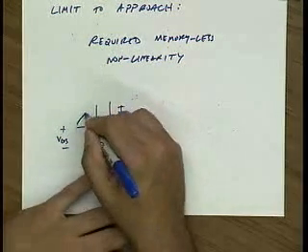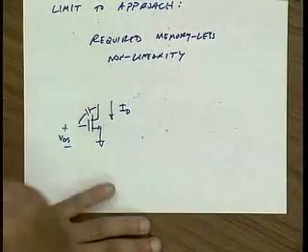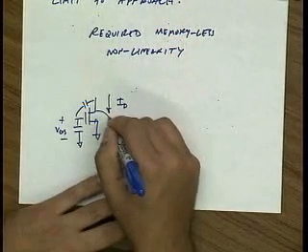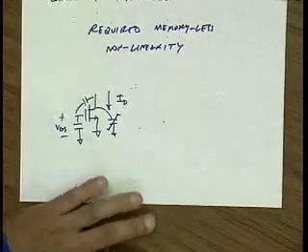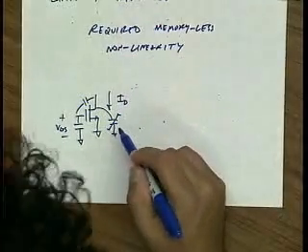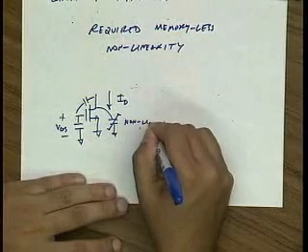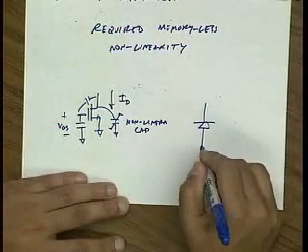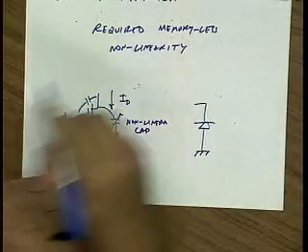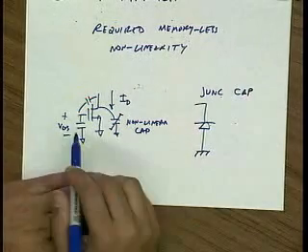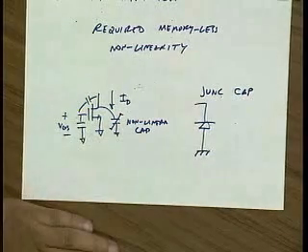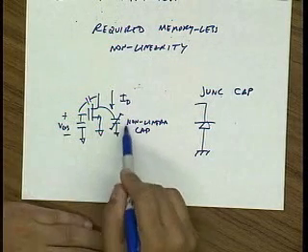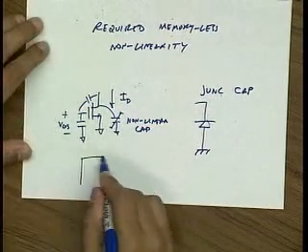So I have this small overlap capacitance, right? I have a CGS here. And then I have junction capacitances, right? Now what's interesting is I put this little slash through here to say that this is a nonlinear capacitance, because this is a reverse bias diode, right? So this is my junction cap. The other capacitors in the system actually look like linear capacitors, right?